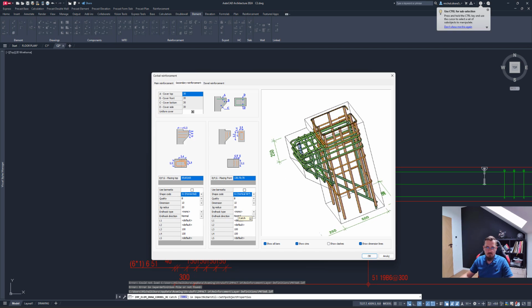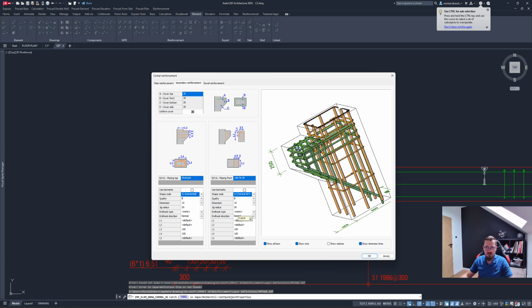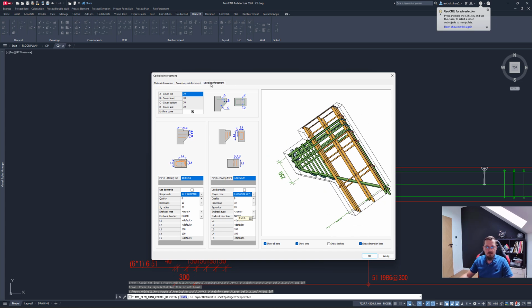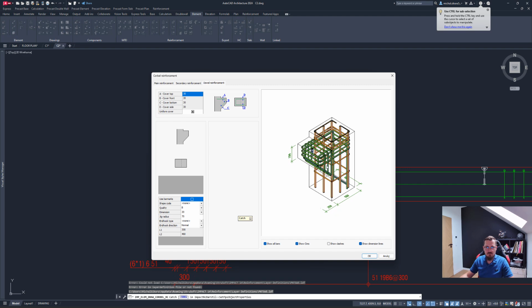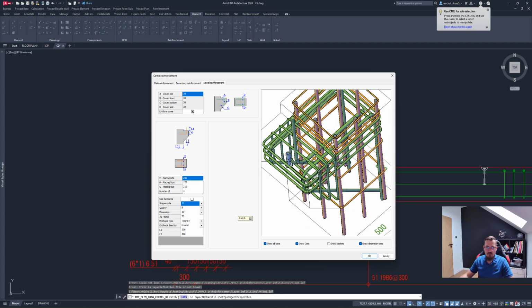So multiple different ways of adding the reinforcement. Let's go with those 51 shapes. And if need be, we can also add some dowel reinforcement just to demonstrate that. So that's a bar like this. If we didn't have a lift here or a connector here, then we could maybe add a hole to the beam for connection. That's a thing that I forgot to demonstrate. We can go back to that in a second. We'll refresh the drawings anyway.